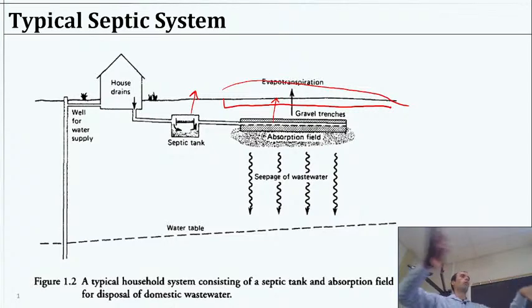More porous, gives you more surface area for your liquid to discharge into the soil. So even if you have a high water table or poorly percolating soil, you can kind of maybe get away with that if you expand it enough. Of course, if you get enough surface area, even very slow percolation can work, right? Even through clay, if you have just tons and tons of surface area, which is very costly, you can make it happen. So there are ways you could always force it to happen, but oftentimes it's not quite economical.